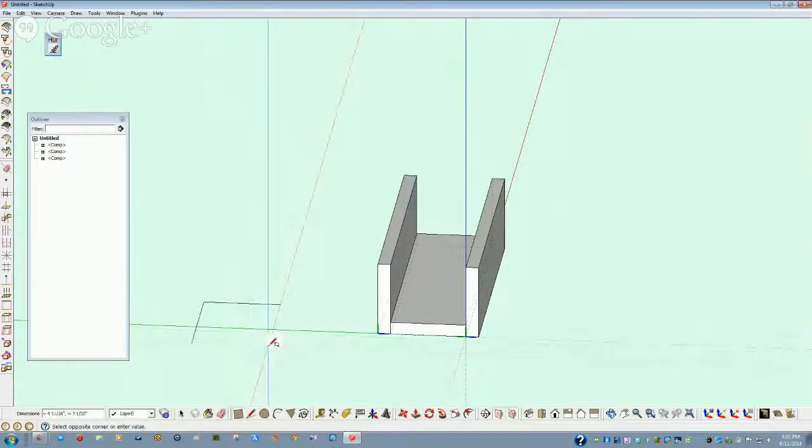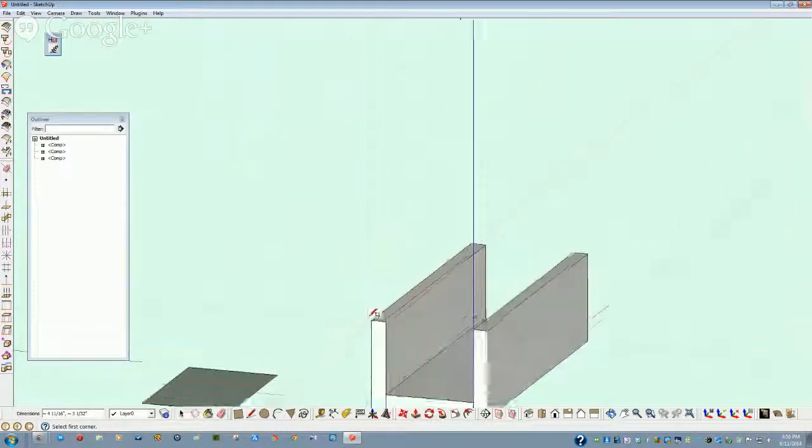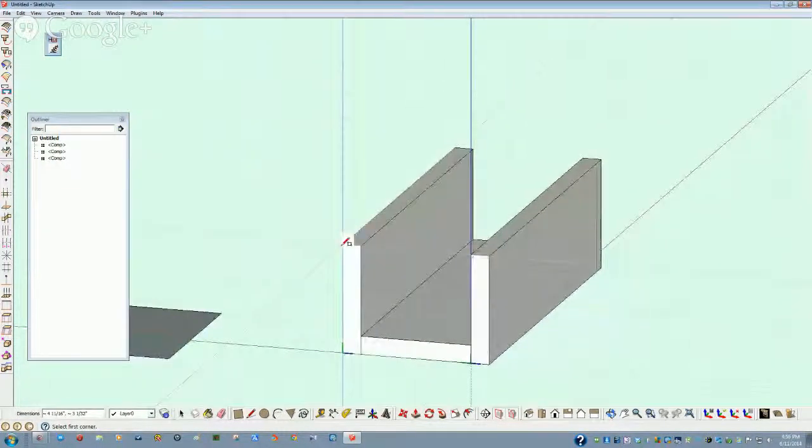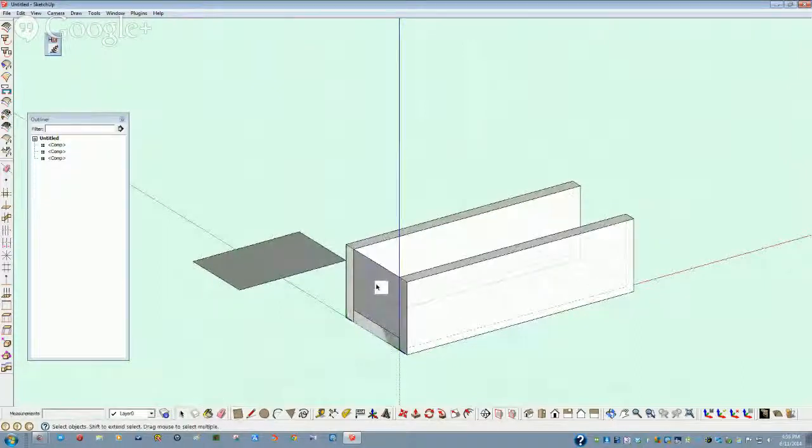You can create one on the XY axis, or if you've got existing geometry there, you can create it from the existing solids or lines. So you don't have to, even though you can change the XY axes, the UCS, if you're conversant with that, you are. WCS, CSIS, all of those things are all the same process.